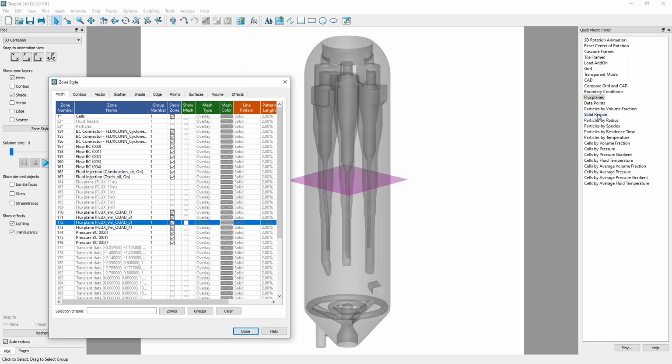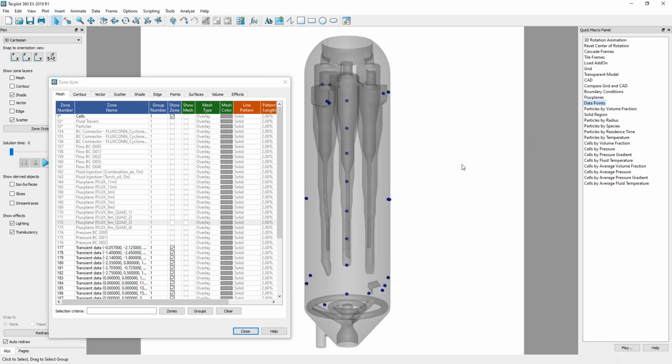The other thing here is data points. And so I'll just point these out. These are high frequency output data that's available from the simulation. And people use these to represent things like thermocouples or pressure taps. And so often you'll put these in your model exactly as you would have them in your physical system so that you can monitor exactly the same types of data from the model.